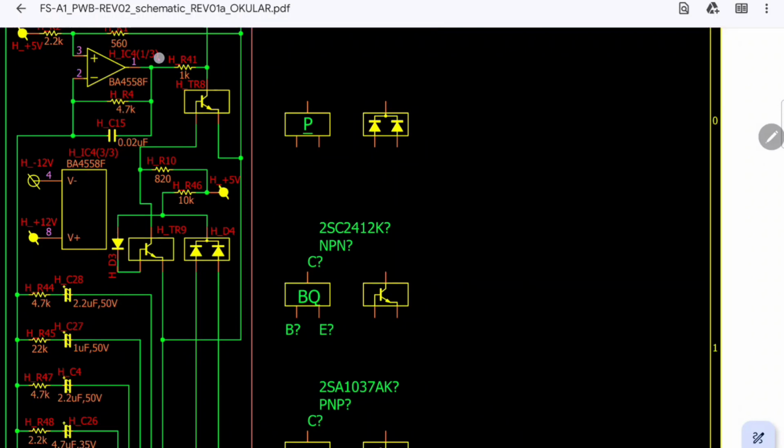Our goal is to know which is the voltage in here. Is the output VO. We know that here we have 1 volt because of the voltage divider with these resistors, and in here we have the input of the different sources of sound, the PSG, PPI, and the cartridges, which are tied together, and they go to the non-inverting input of the op-amp.